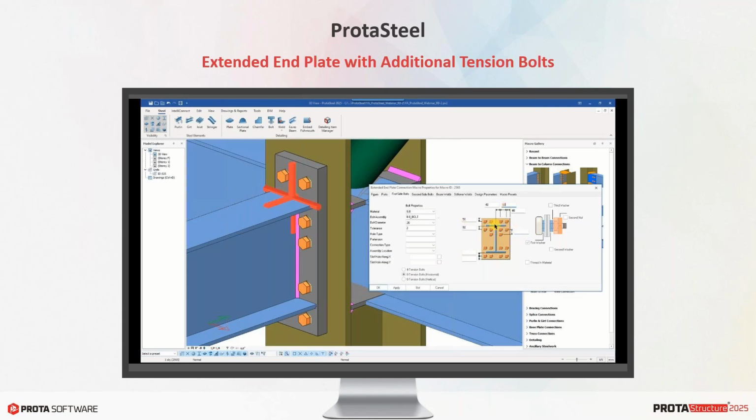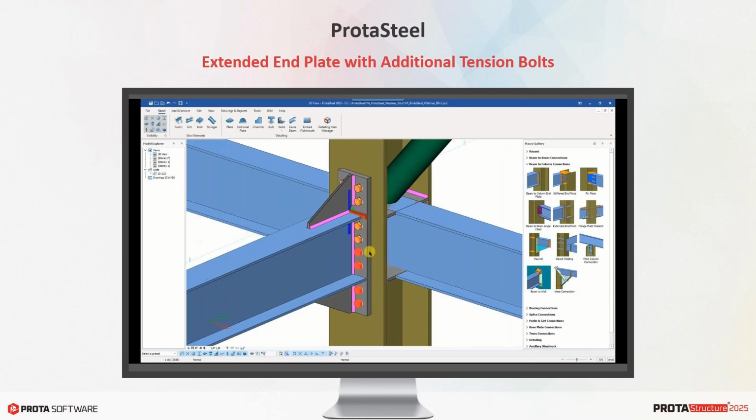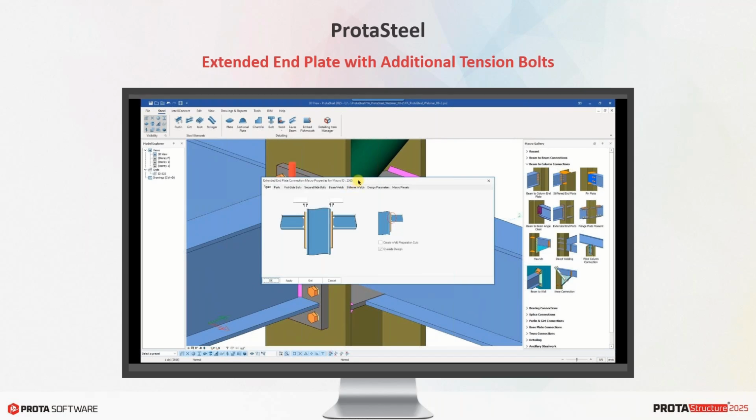In this connection, the internal bolts between the flanges of the beam are used to attach the end plate to the beam and the column flange. The end plate extends beyond the column flanges, allowing the use of bolts other than the interior ones. In the new ProtaSteel, you can now increase the number of bolts in the extended plates outside the beam flanges.